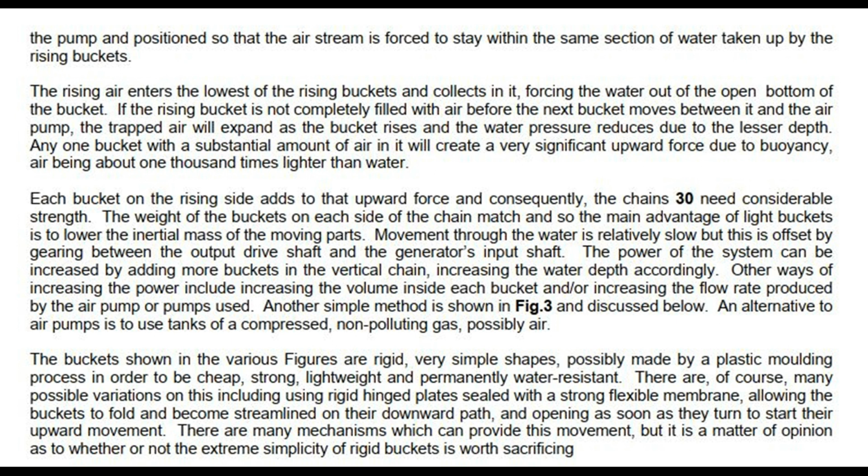There are, of course, many possible variations on this, including using rigid hinged plates sealed with a strong flexible membrane, allowing the buckets to fold and become streamlined on their downward path, and opening as soon as they turn to start their upward movement. There are many mechanisms which can provide this movement, but it is a matter of opinion as to whether or not the extreme simplicity of rigid buckets is worth sacrificing.